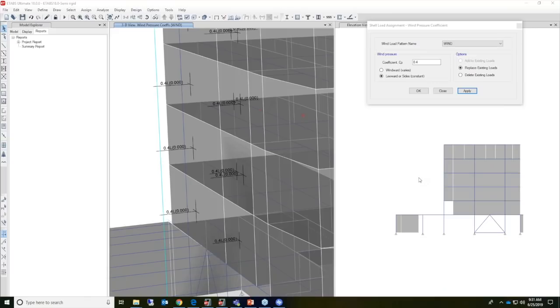Okay. Oh, here we go. When do you need to assign diaphragms with different names, perhaps D1 and D2? That is if you really want two portions of the building that are connected by some flexible members. You can have two or three or more diaphragms assigned to each floor, and each one of them should be given different names, and then you can have some flexible members connecting them. Or you could even have two towers that go down, and you may want to keep those separated.